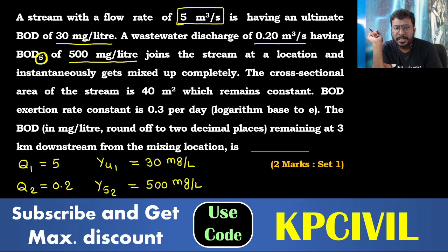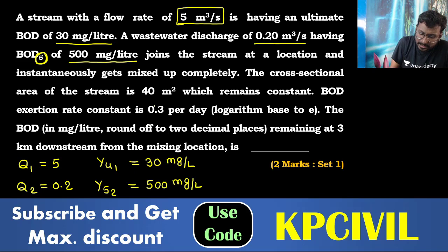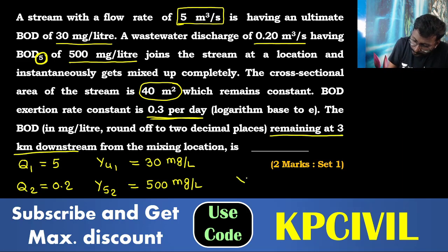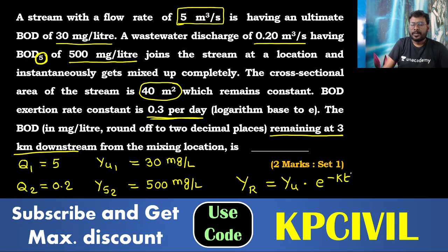It joins the stream at a location and instantaneously gets mixed completely. Cross-sectional area of the stream is 40 meter square, which remains constant, not changing. BOD exertion rate constant 0.3 per day, logarithm to the base e, the k value. The BOD remaining at 3 km downstream. So Yr, BOD remaining. What is the formula? Ultimate BOD into e power minus kt. Simple.